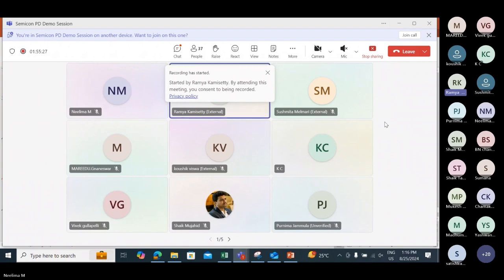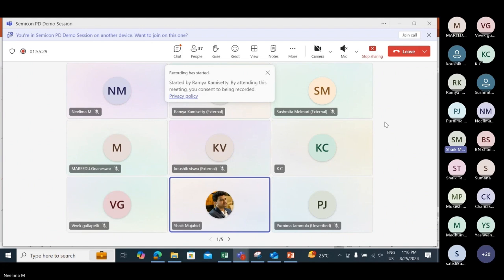Mujahid, you are about to say something? Yes, just an add-on to the discussion we had, regarding silicon and germanium comparison. As in your graduation, you might have heard that silicon is more preferred as a semiconductor material compared to germanium. We know the nature of a semiconductor when it comes to conductivity: conductivity is between insulator and conductor. If our main motto was to just conduct electricity, we might have opted for conductors. But silicon is a better semiconductor than germanium because its band gap between valence band and conduction band is more than germanium.